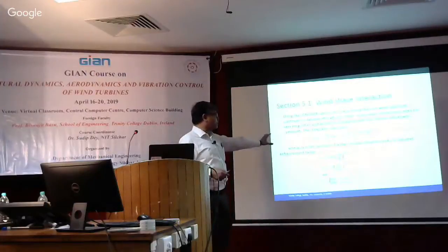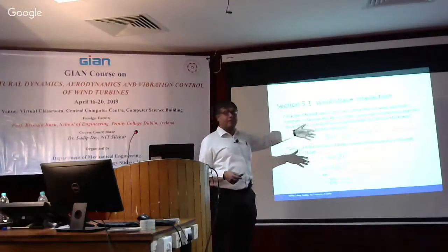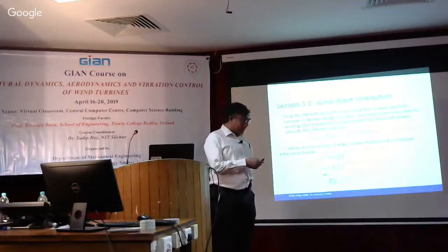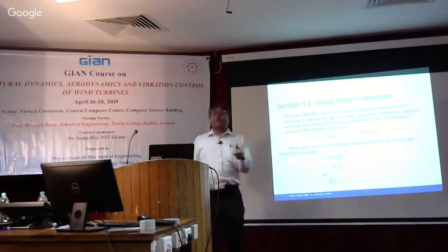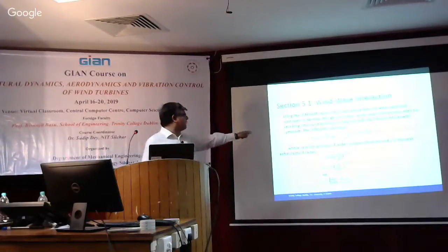Once you have the spectrum, you can take an inverse Fourier transform and generate the wave loading. You can then use this U10 also to generate your wind loading. That means your wind and wave loading are now correlated by using the same U10 value.